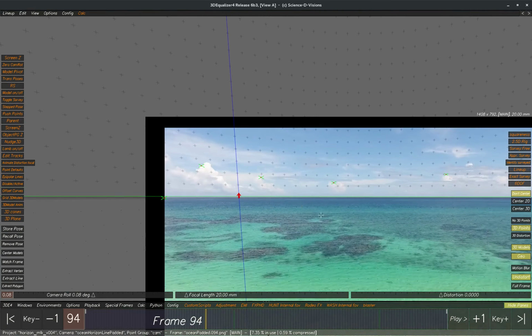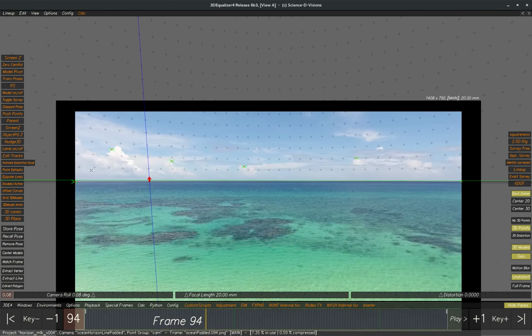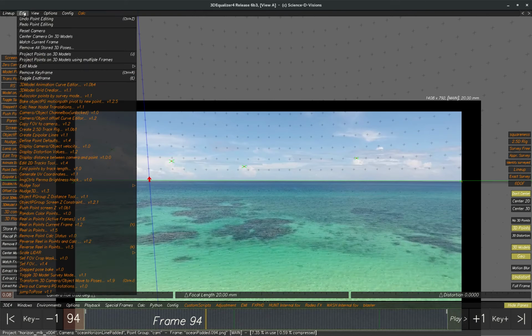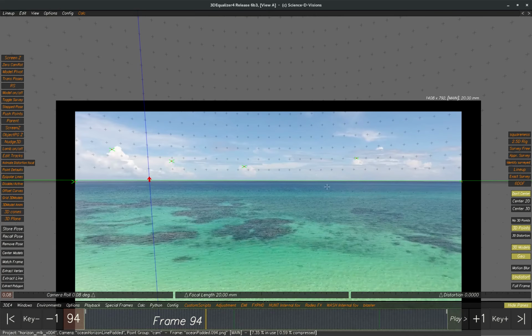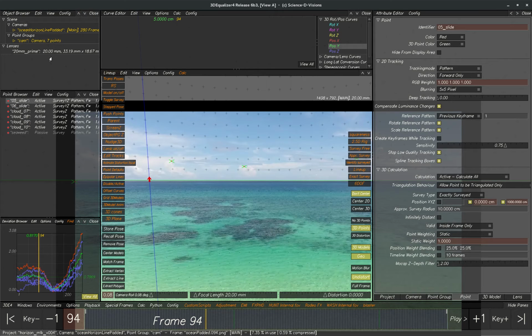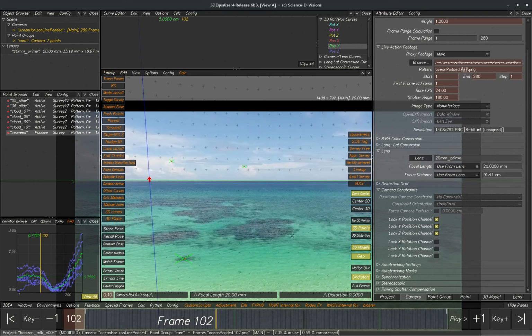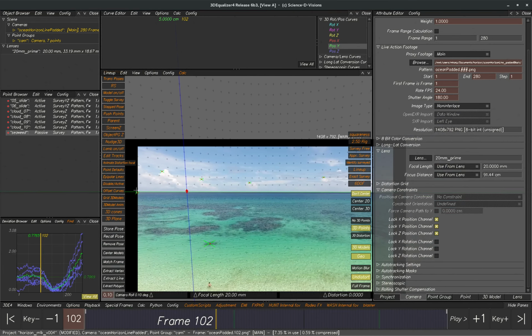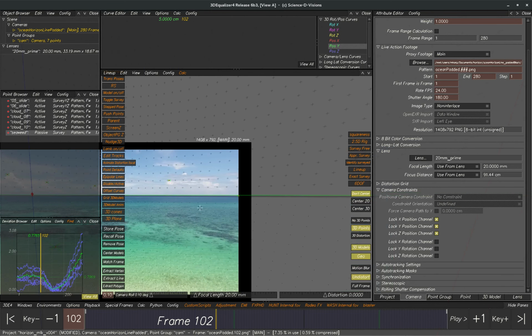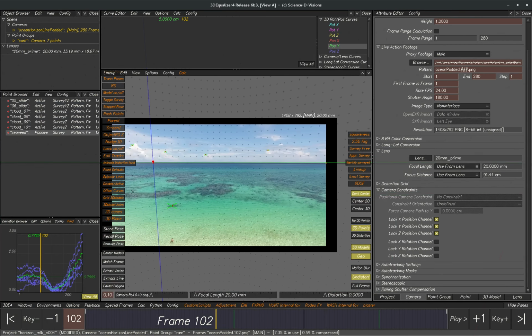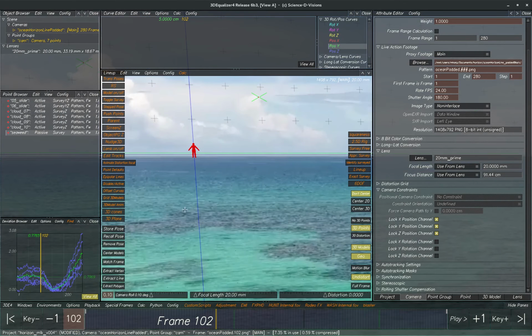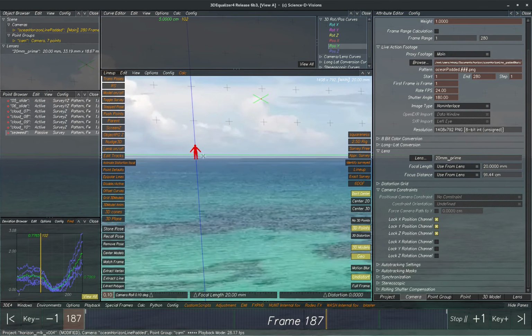So once you get these points here locked at infinity, then you could reel them in here, and after that, then you could start figuring out what your actual focal length is, and then you could track foreground points. You can take the camera out of the sort of nodal situation we're in here, because again, once you get this point baked with a reel in and this point baked, then you've got the raw materials to do a full 6-degree free move. Again, looking at this, the point is we want a ship or whatever it is on the horizon line to lock.